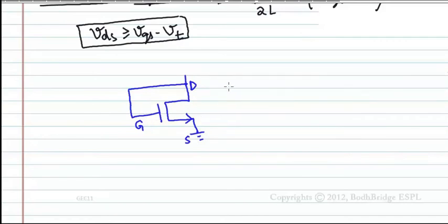Here you see, we want to first check VDS. This is Vx, it is given. Looking at the upper circuit, VDS equal to Vx minus Vs. Vs is 0. And VGS: G is connected to drain, therefore VGS is also Vx minus 0.